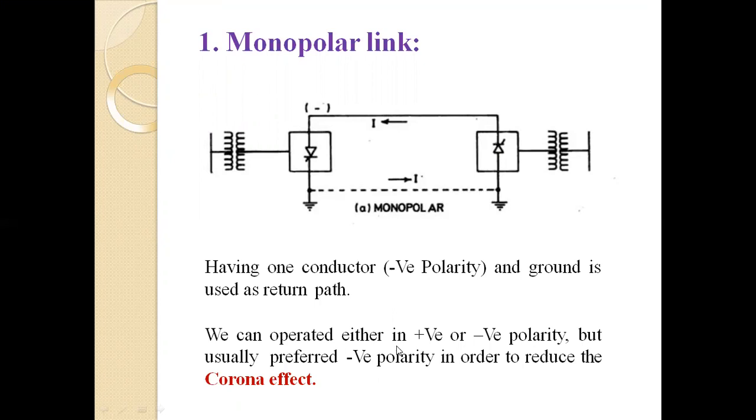We can operate either in positive or negative polarity. We can take either positive polarity or negative polarity. But usually we prefer negative polarity in order to reduce the corona effect. For reducing the corona effect, we take the negative polarity and positive as a ground.